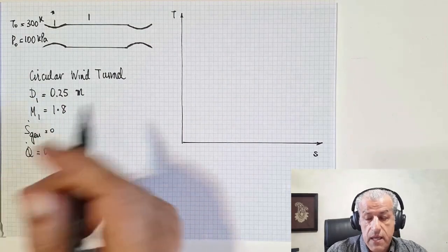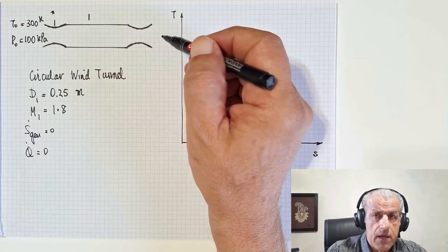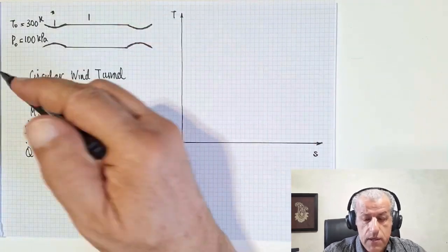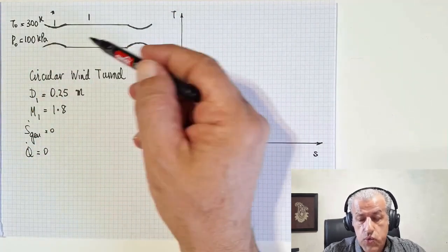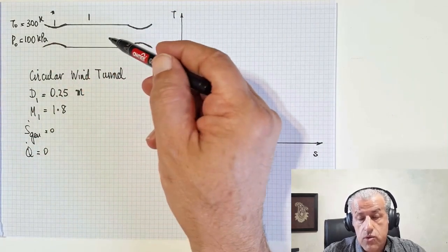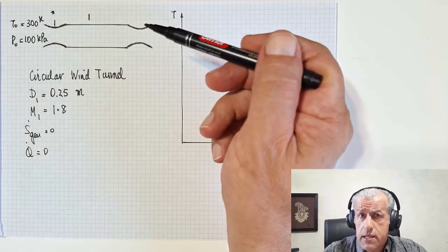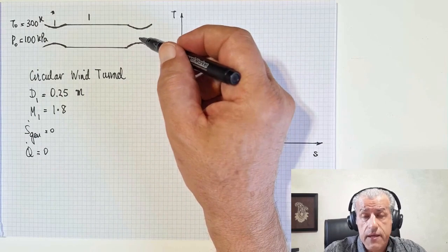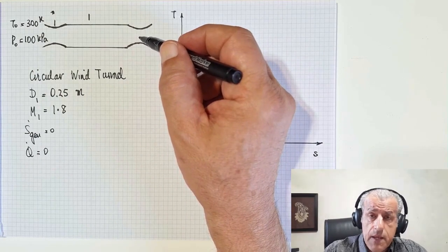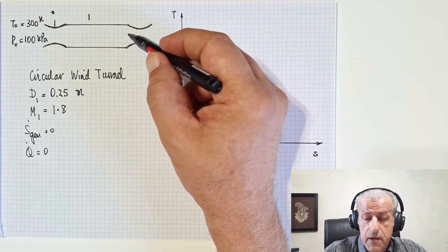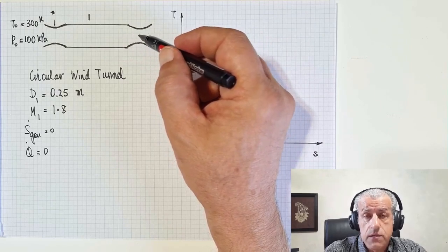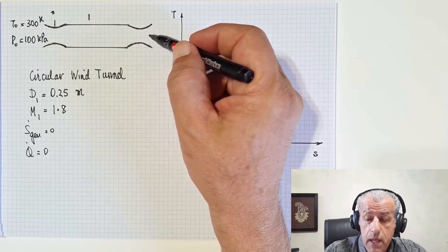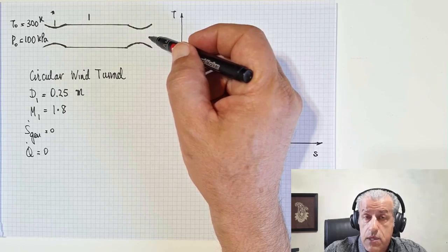It means that there is a fan at the end of the tunnel continuously drawing air from the atmosphere, going through the nozzle, through the test section, and ideally there is a supersonic diffuser where the flow returns to sonic, to the throat at Mach 1, and then continues subsonic.